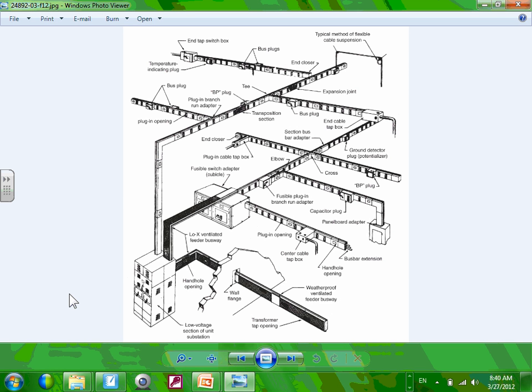The best wiring method for this application is to run a 480/277 busway right above your head with disconnect switches and fuses, and have an SO cord, hard usage, tie directly to each one of you as a machine. Does that make sense? That's really the main use of busways.